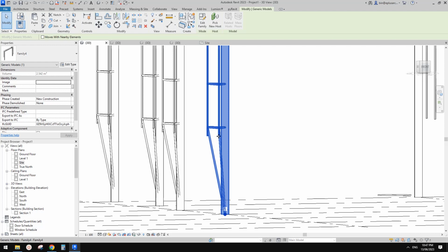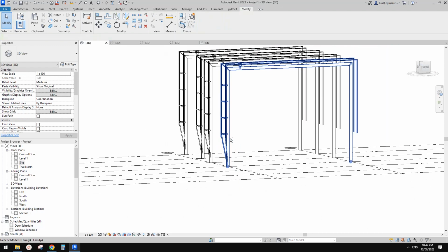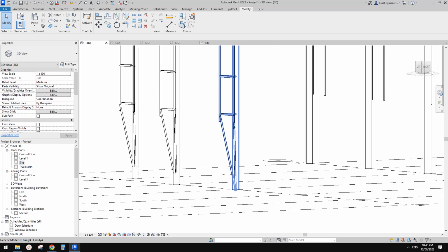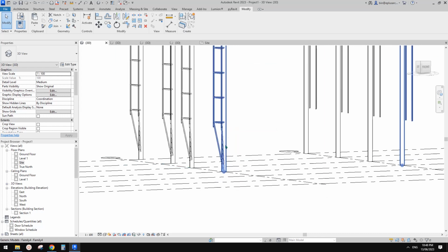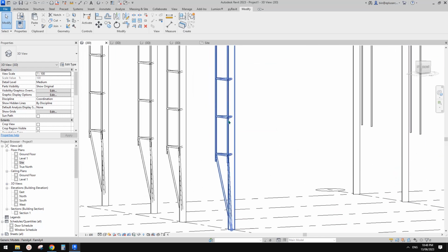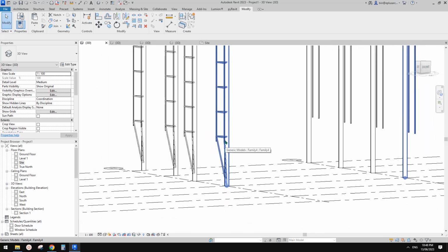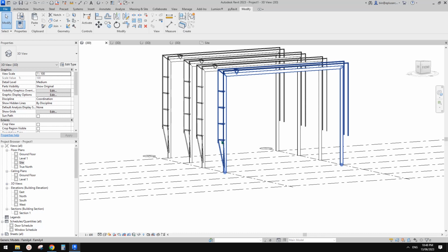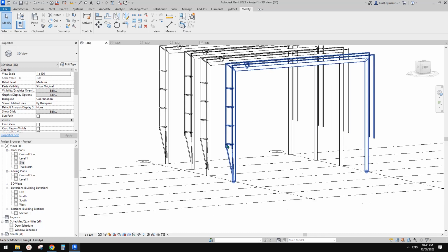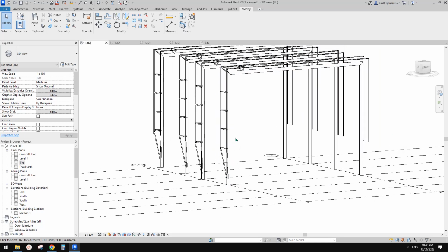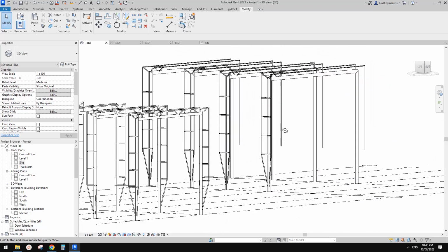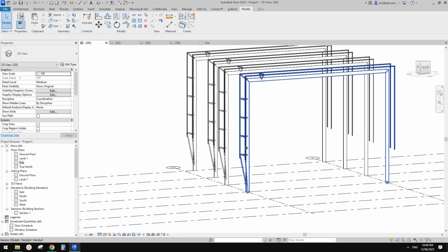I think it's because when we created this sweep, we used a point with a 3 meter segment length, and for this we used normalized curve parameter. Because we are using different methods, that's why we have this issue. But we just need to pick one and use the same method. So that's not a big issue.